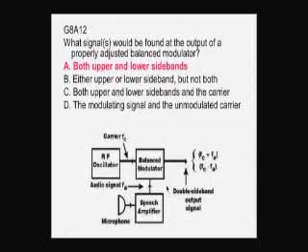Now, the beauty of the balanced modulator is that it eliminates the oscillator signal, the carrier signal, that in an ordinary mixer would be coming on through. The RF oscillator frequency cancels out in the balanced modulator, so you get only the upper sideband and lower sideband signals. And that's how we generate double sideband, which we then filter off one sideband to make the single sideband.